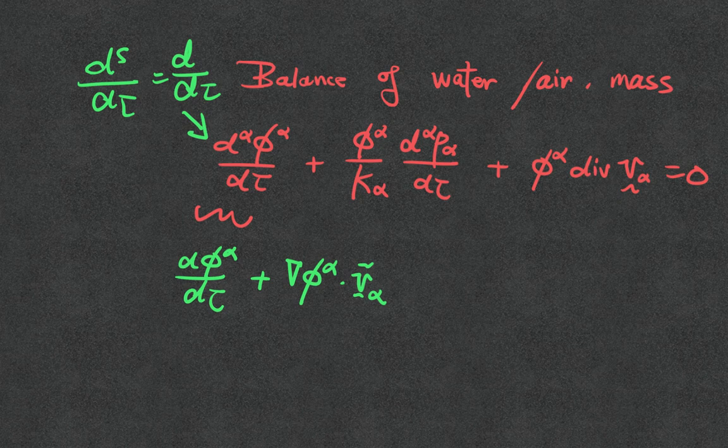Now alpha is the Darcy's velocity, but now I have two Darcy's velocities: the Darcy's velocity for the water and the Darcy's velocity for air. Does that make sense? Because the air and water don't necessarily move together. They can move in different directions, or they can flow relatively similarly, but they may not be traveling at the same speed.